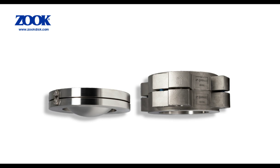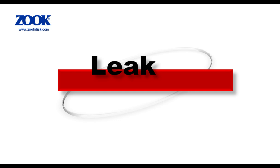It turned out that in order to reduce cost, the inlet side of the holder had been reduced to a point where the disc dome protruded beyond the holder face, similar to the assembly on the left. This can create problems during installation, as it is easy for the dome to be impacted during handling and insertion of the assembly between flanges. This can go undetected until it results in a service issue, and this is what was happening. Our solution, on the right, was to simply provide an assembly with a similar disc style with a pre-torque holder that sealed the disc and fully protected the dome. Problem solved.